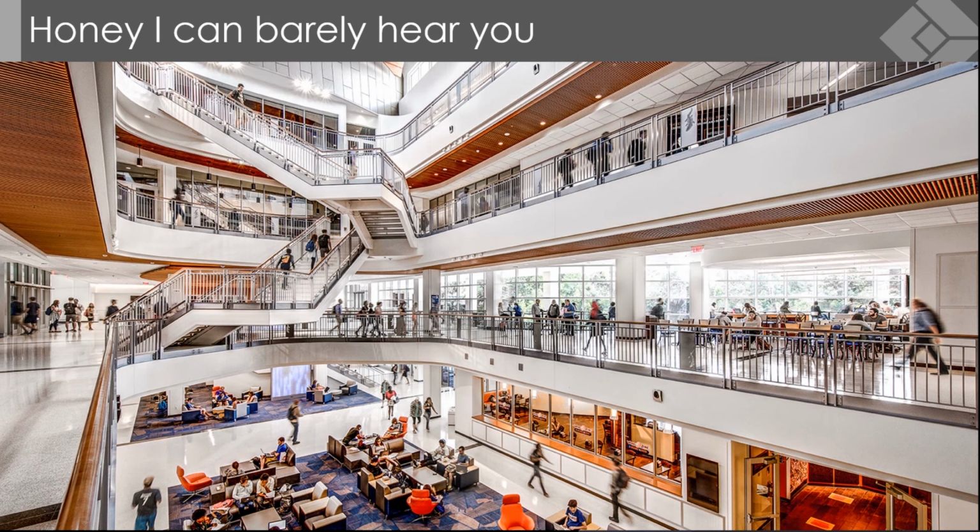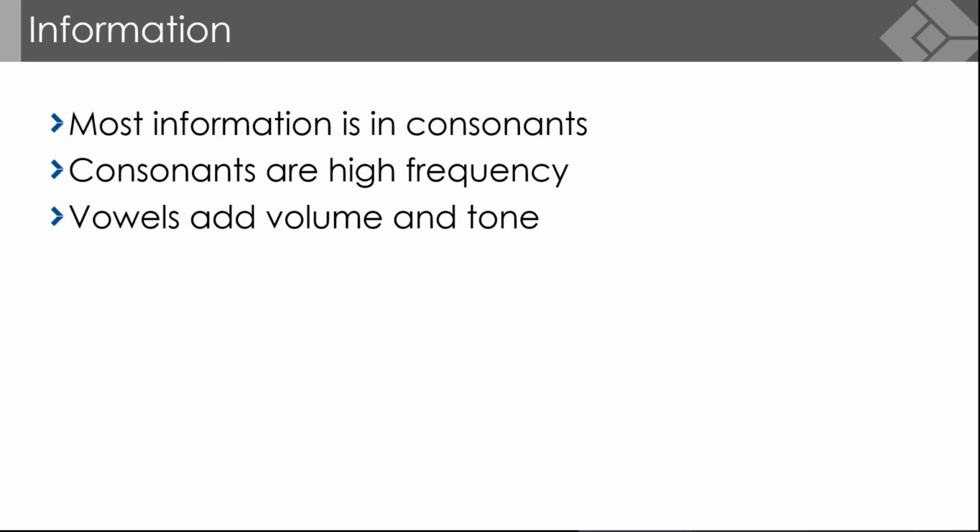And when you look at a noisy environment, most of the information in human speech is in the consonants. It's the t, sh, k, where most of the information is. The vowels add volume, but mostly the consonants give you information. And the consonants are all the high frequencies.